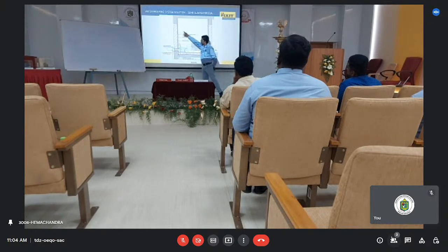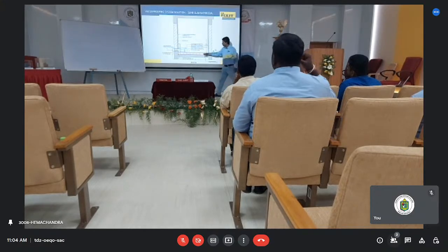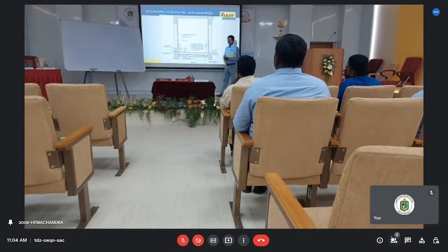If it is special, 7 feet height also. Then protection screed, then filling with prepared or cinder filling. Then plaster, then tile adhesive and tile joints with grout of epoxy. So this is a typical cross section of the toilet waterproofing.